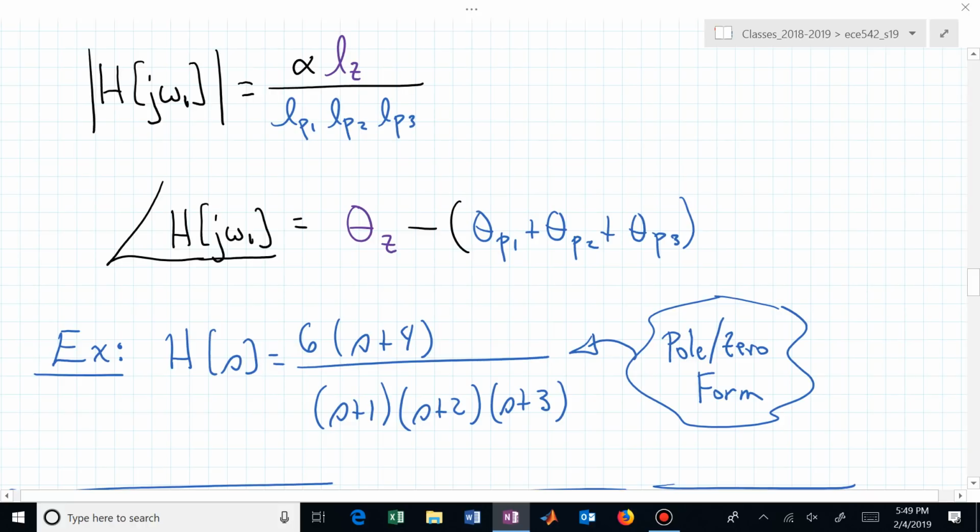of zeros of 2. That's not so important, but now what's the DC gain of this transfer function? I heard a 4. Where did 4 come from? Just evaluating H of s when s is equal to 0. And we have 24 divided by 6. And the last time I checked, that was 4, wasn't it? 4 times 6 is 24. So this has a DC gain of 4.